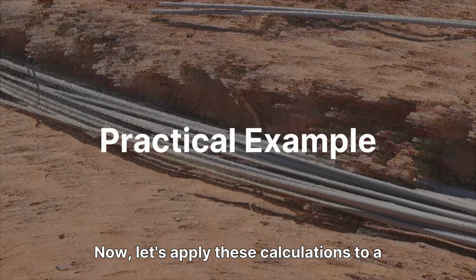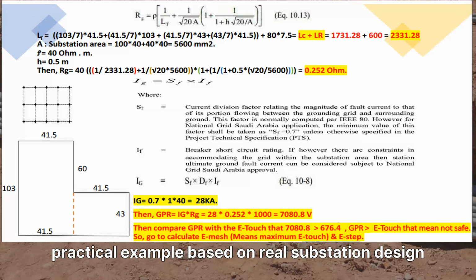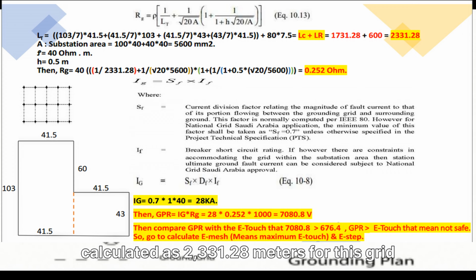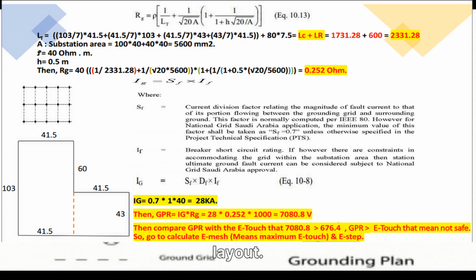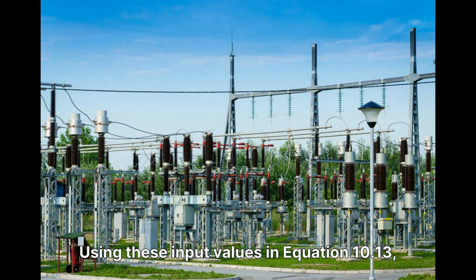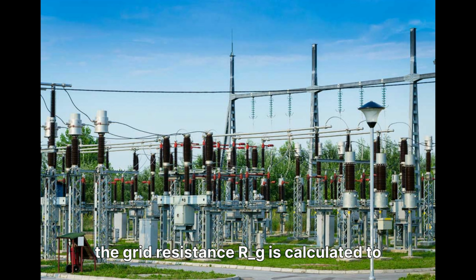Now let's apply these calculations to a practical example based on real substation design parameters. Given specific dimensions and resistivity values, the total buried length of conductors L_T is calculated as 2,331.28 meters for this grid layout. The substation area A is 5,600 square meters, with an average soil resistivity ρ of 40 ohm-meters and a grid depth H of 0.5 meters, excluding any asphalt. Using these input values in equation 10.13, the grid resistance R_G is calculated to be 0.252 ohms, which is below the 1 ohm target.